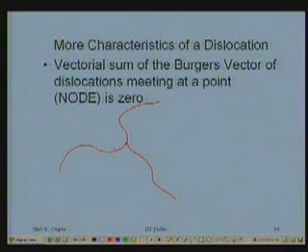So this dislocation is going toward the node, then the T vector is this, going towards the node, T vector is this, and going towards the node, T vector is this. So T vectors are chosen like this. Either I take them going towards the node or I take them going away from the node. In either case, if I work out the Burgers vectors and sum them up, the sum of the three Burgers vectors would turn out to be 0.